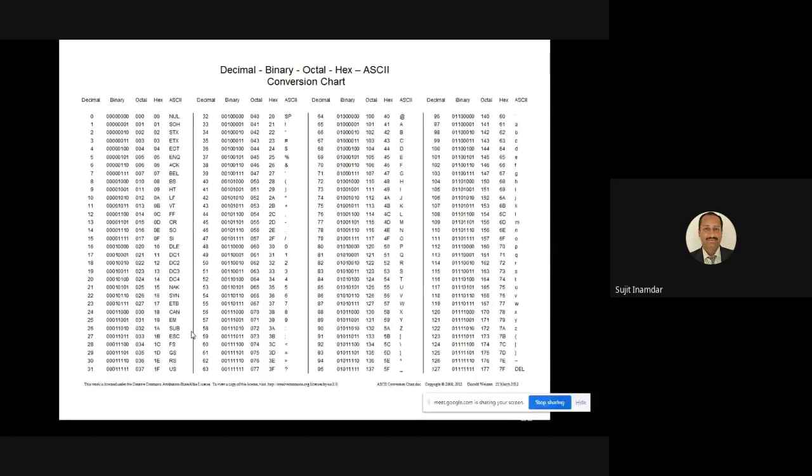So for that we have to pass the respective ASCII code or binary, because as we saw in yesterday's circuit diagram, 8 data lines are there for the LCD display, through which the 8051 is connected to the LCD display, and we have to give the command through the 8051. In code we are just writing A B C D or 1 2 3 4, so that has to be converted into the respective binary.